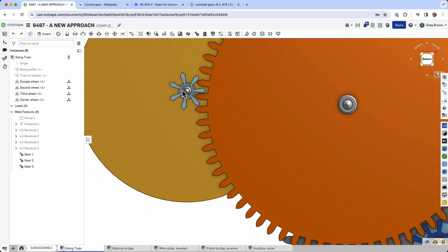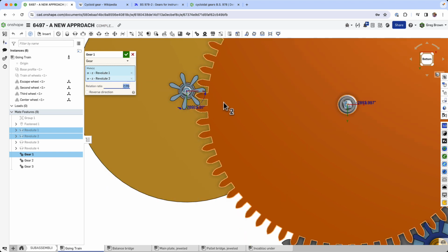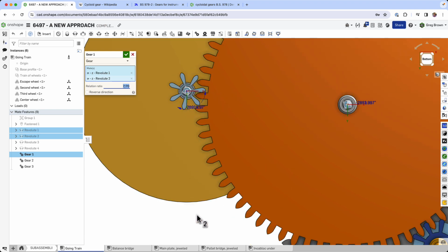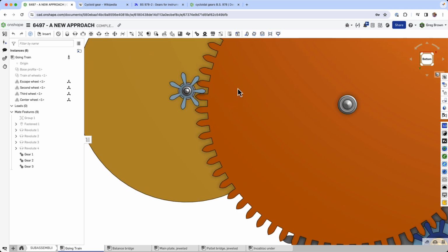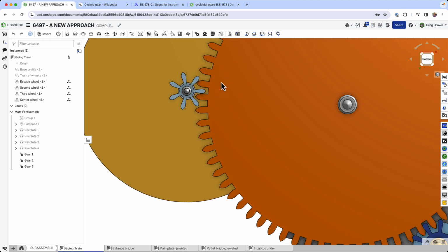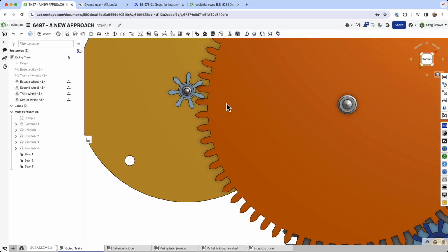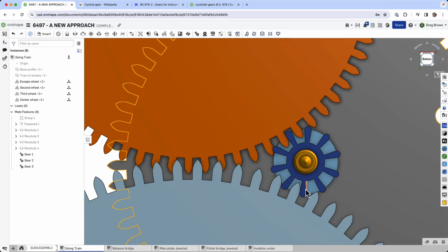It's a joke. It will, and because these gear ratios are based on the number of teeth, and these things were designed as pairs, so they've got their pitch circle diameters perfectly created according to the standard, they will mesh nicely like this. And so, even though it is completely, at this point, eye candy, it's nice. It's nice to see nonetheless. And you don't want to see interferences here or things going at the wrong speed or in the wrong direction. That's the same for all of these other gear pairs as well.